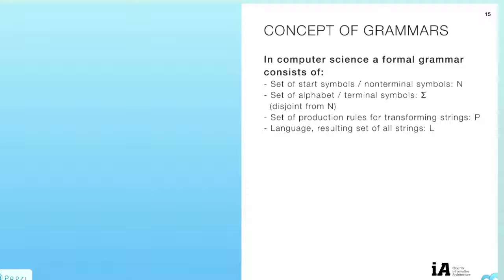And then we have a so-called set of production rules. These are basically the set of all rules that we have inside the CityEngine grammar file, the rule file. And the whole construction, so to say, the whole rule file, represents the language. It's a very specific language that you have created to formulate a specific design, or at least a design space. Since it's parametric, different possibilities can come out of this code, and therefore you could even say design space.